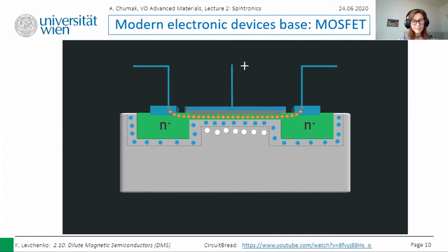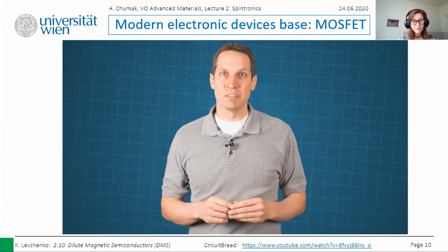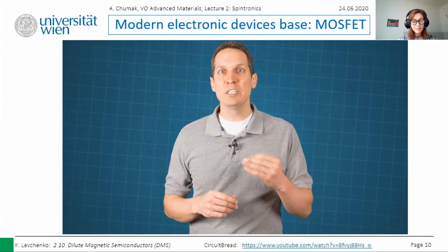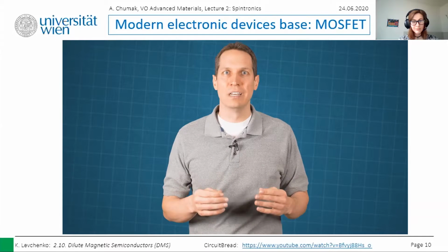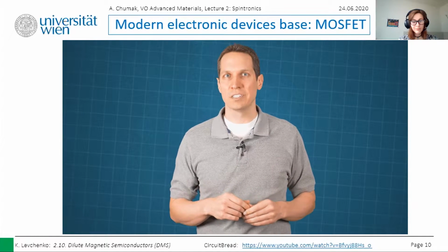This is how, using a metal oxide semiconductor structure, you can use the field effect of a gate voltage to create a semiconductor switch. And to get a PMOS device, you have an N-type substrate and heavily P-doped wells for your source and drain, and the current carriers are holes instead of electrons.